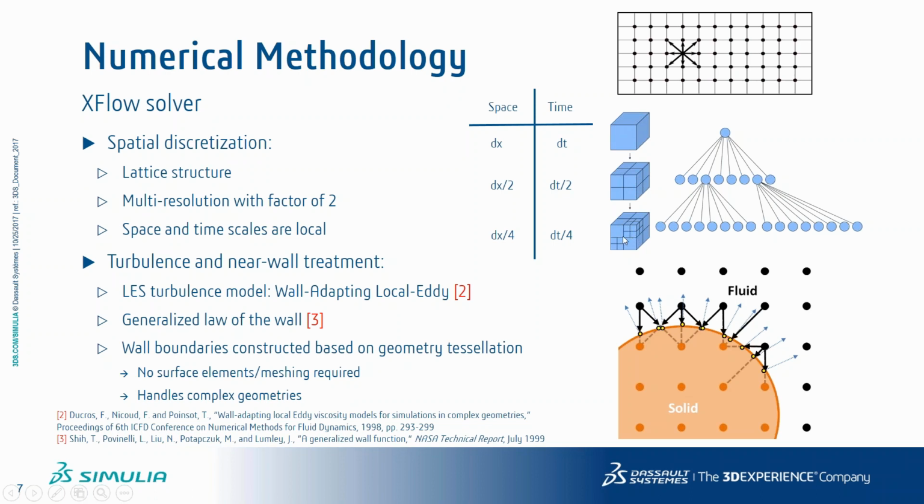Okay, so let's say the time steps, not only the spatial scales but also the time scales, are divided the same way, following the same ratio. Every time you divide the space by 2, you divide the time by 2, and so on. So you have a constant dx over dt ratio across your entire domain, so a constant CFL condition, for instance.